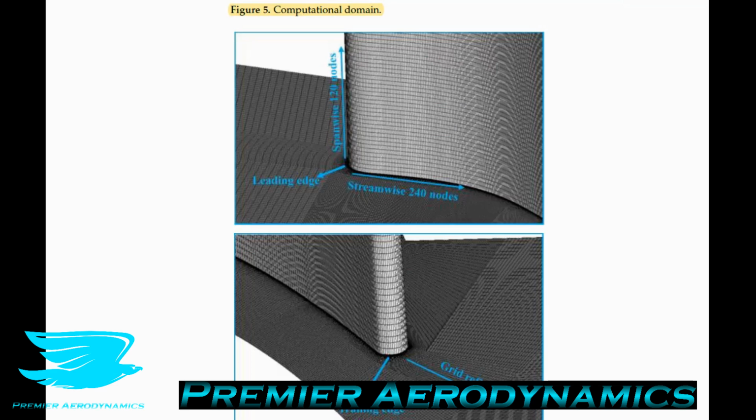Then we have the separation bubble transition, which in my experience is the hardest out of the 3 to model. I've done podcasts on this, but this is where you have flow going over the airfoil or any surface, and it's laminar. Then it separates, then it reattaches, and by the time it reattaches, it's turbulent now. And in this point where it detaches to reattaches, you have this circulation bubble, this recirculation dead zone. And this effectively increases the camber of whatever you're using, and it can increase the lift coefficient dramatically. There are some benefits to it and some detriments. I've covered that in another podcast, I won't go through it here, but that's that transition path.